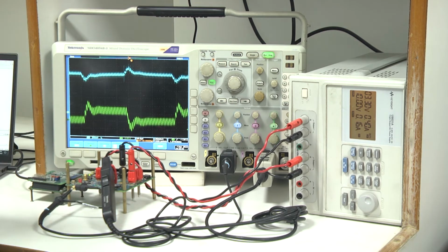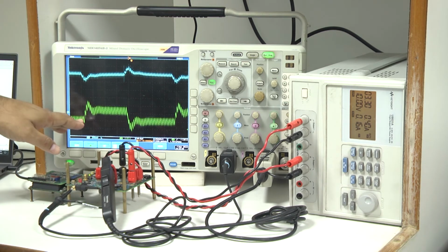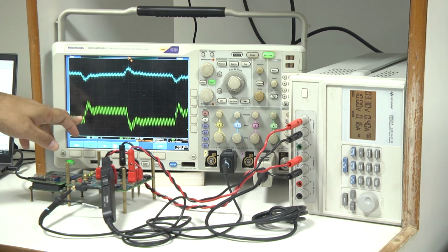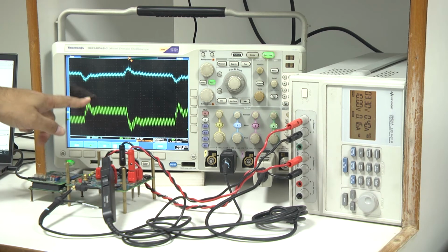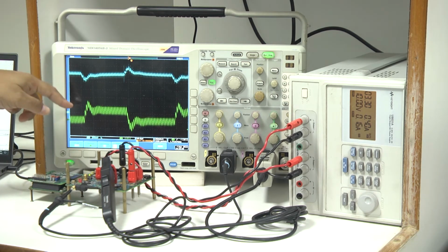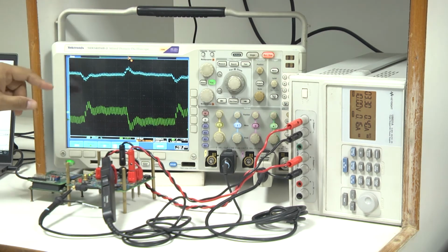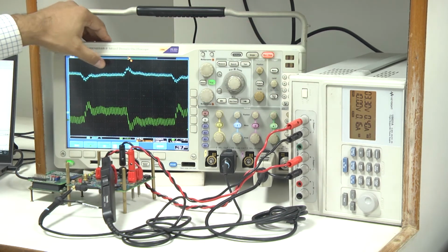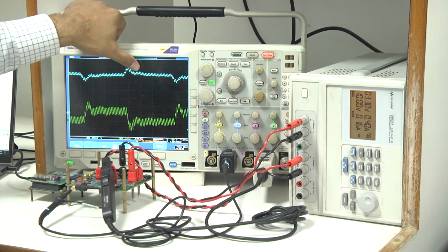How? We have added a parallel resistance of 0.33 ohm with the 13.5 ohm. So, effectively it was becoming like 0.32 ohm. So, this has created a load step of roughly 3 ampere. You can see the current load step happening, and because of the load step transient there is a voltage undershoot. If you just stop it, you can see the voltage undershoot at 3.3 volt input, and then it is followed by a load step down transient.